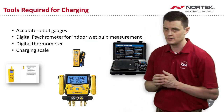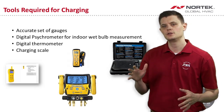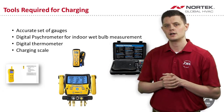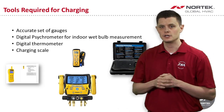Also, with the new charging calculator and the new charging charts that we'll take a look at, the biggest thing we require in tech service is an indoor wet bulb, and that is done via a psychrometer.